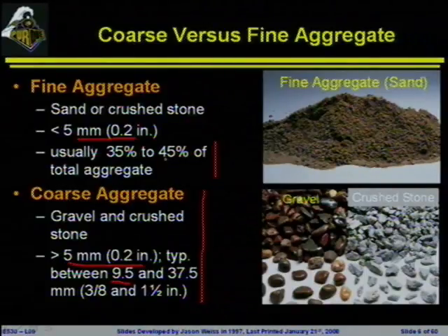Now, you will see, like most things in the concrete community, the pendulum has shifted backwards, and people have said, why are we using these small aggregates? We should be using larger aggregates. Why would we want to use larger aggregates now? Other than the fact that people can't read journals that are 15 years old. It saves energy. It saves the energy of crushing. It has another big benefit.